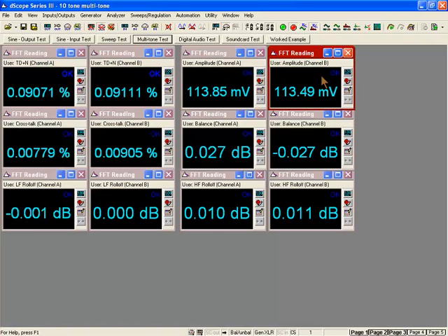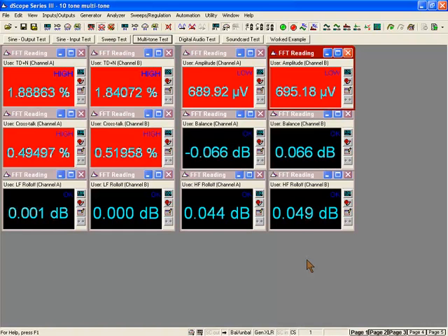And if I just crudely emulate a fault in my tablet device by turning the volume down, I can rerun this test. So there's my file still playing out. I can rerun the test at a lower signal volume on my tablet, and now we see that the device has failed test. That was a very quick test that took a couple of seconds, and instantly we've got all of this information and critically the information telling us that this particular device failed test.